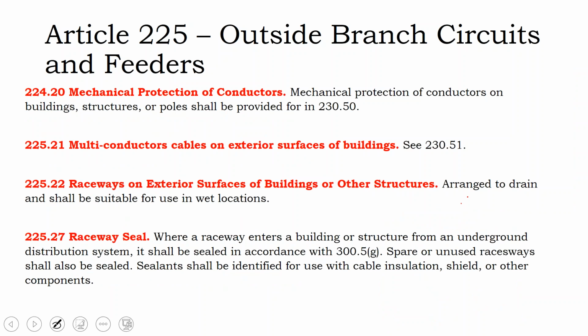The main thing on your raceways is they need to be arranged to drain. You don't want water tracking down a raceway and getting into your boxes. We talked about the raceway seal. That's a very common exam question.